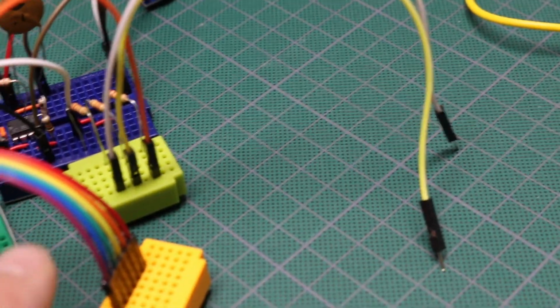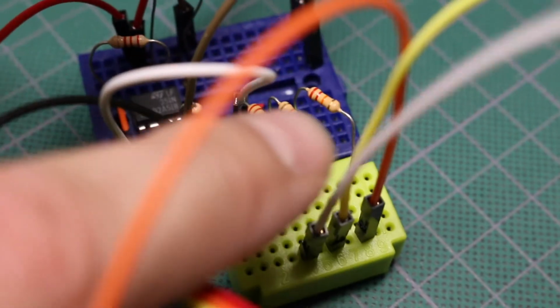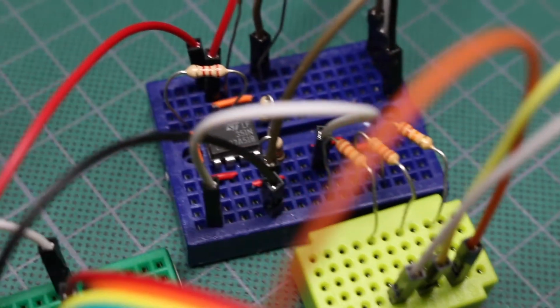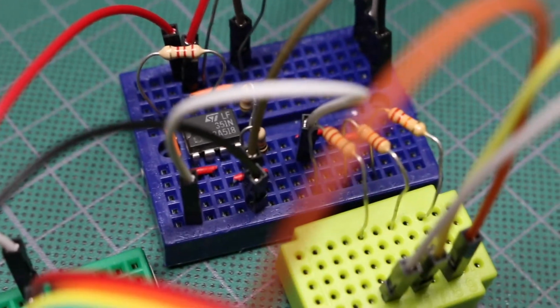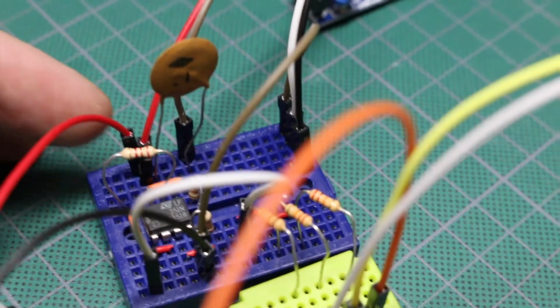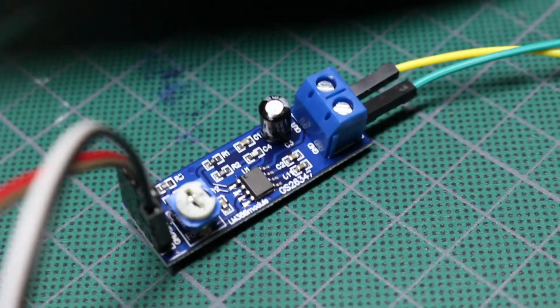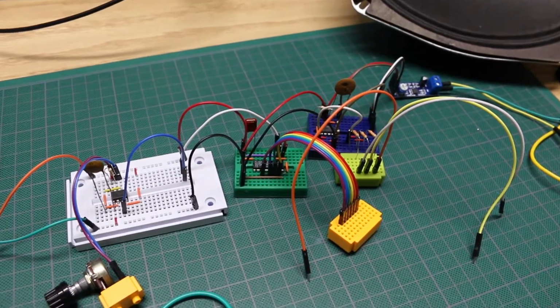And those go to this other small breadboard, and that is the op-amp mixer. I ended up using 22K resistors on the input of each channel on the mixer, and a 2.2K resistor on the feedback of the op-amp. Then I put a 0.1 microfarad DC block series capacitor at the output of the op-amp, and it goes over to the input of this 386 power audio amp and to the speaker ultimately. So let's see how it sounds.